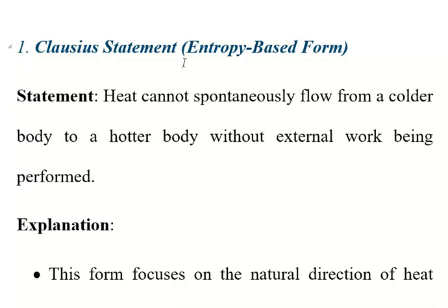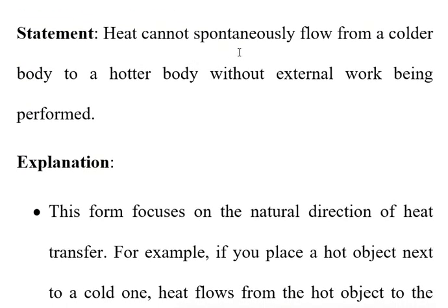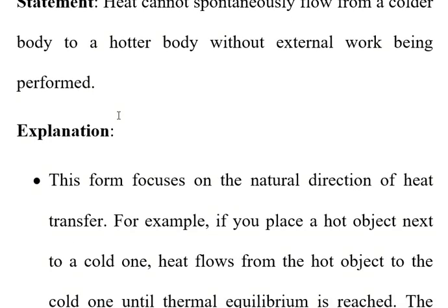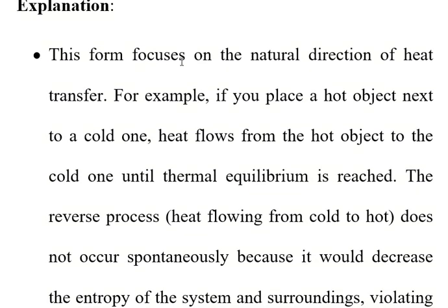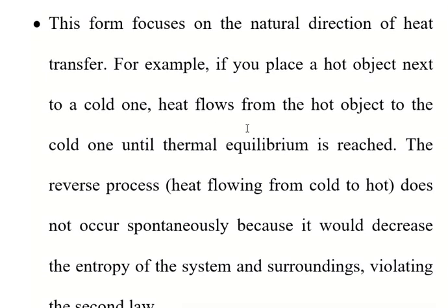The Clausius statement is basically the entropy-based statement of the second law of thermodynamics. Heat cannot spontaneously flow from a cold body to a hot body without external work being performed. The best example of this statement is the refrigerator, in which we provide electrical power and heat is moved from the cold body to the hot body. The hot body is our surroundings, the fridge is our cold body. This statement focuses on the natural direction of heat transfer. For example, if we place a hot object next to a cold one, heat flows from the hot object to the cold one until thermal equilibrium is reached.